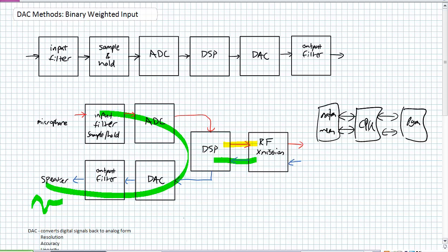The easiest way to describe it, I guess, you've got a string of bits. I think you've got a positive maximum, a zero, and a negative maximum for your analog signal you're trying to represent. And let's say you've got a 3-bit system. 3 zeros represents the negative maximum. 3 ones represent positive maximum. What's the middle? Obviously the middle of that range. What sigma delta or delta modulation means is basically a use of a little bit of feedback with a digital to analog converter.